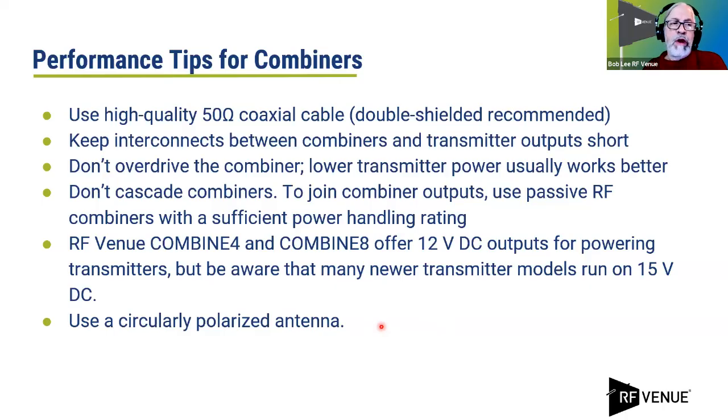The last tip here is to use a circularly polarized antenna. If you've gotten any of our other trainings, like our RF boot camp, or seen some of our webinars on antennas, you know that circularly polarized antennas are really wonderful things. They're really great for in-ear monitors because they transmit a signal that's present in all angles of polarization simultaneously, so regardless of how the in-ear monitor receiver antenna is oriented, it'll pick up the signal really well.